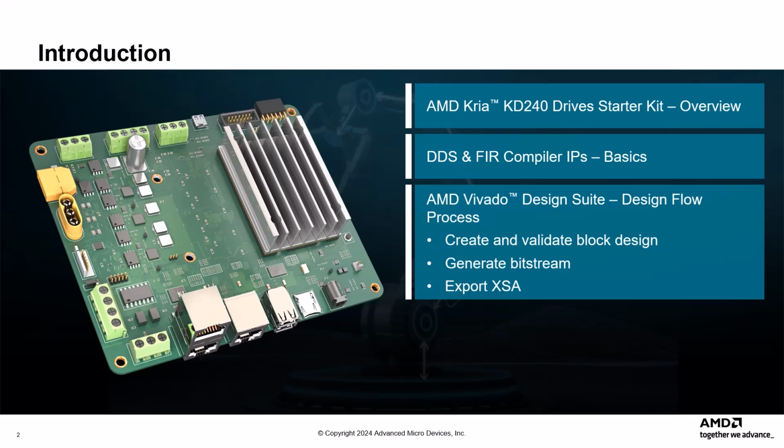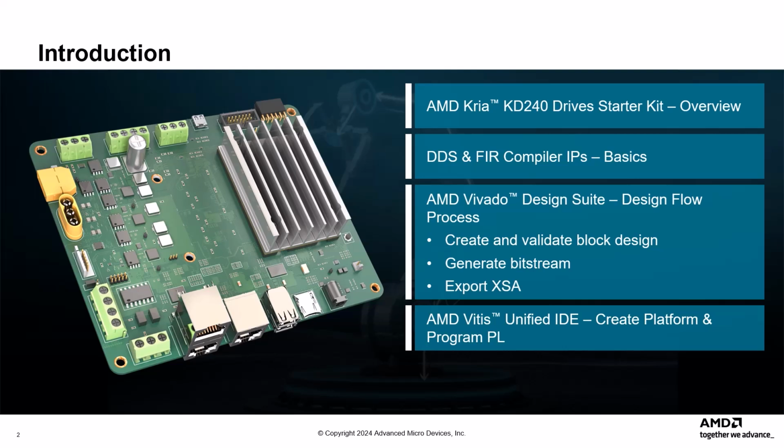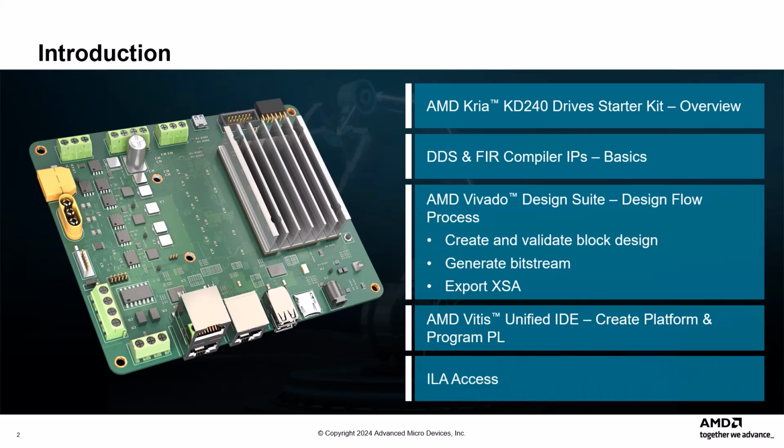Then, we'll show you how to create a Vitis platform using the exported XSA and how to program the programmable logic with the bitstream. Finally, we'll show how to access the ILA from the hardware manager of the Vivado IDE.